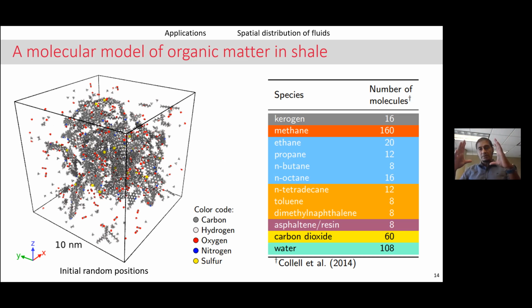and increase the temperature and keep compressing the simulation box virtually so that things bend and the molecules rearrange themselves, and then finally reach a configuration which is an energy minima. And of course, this is a complex process. From this start to the model I'll show you on the next slide can take up to about 2 months, okay? And the scale, again, I want to emphasize over here, 10 nanometers across, not large by any means.